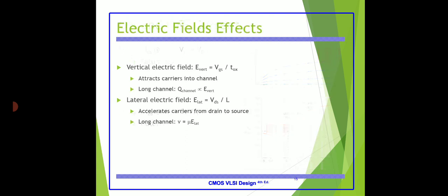Here you can see the two equations for when the current is in the on state as well as in the off state. If the current is in the on state, it is equal to IDS with respect to the gate source voltage, where VDS will be equal to VDD, and we say that it is the saturation region. In the case of off, the current is equal to IDS with respect to VGS, where VDS will be equal to VDD, which determines the cutoff region.